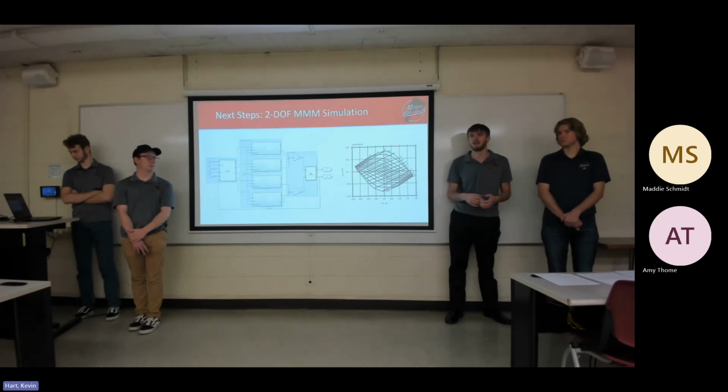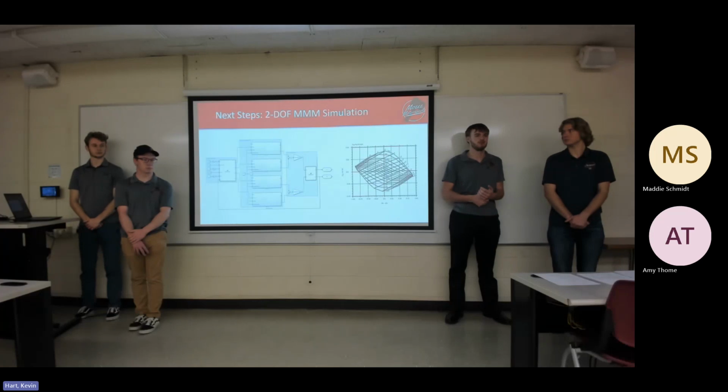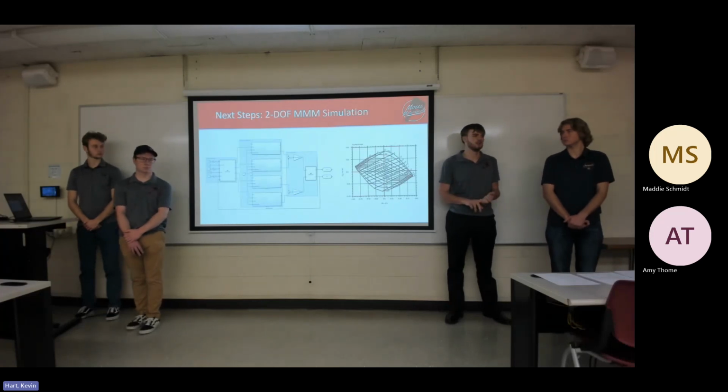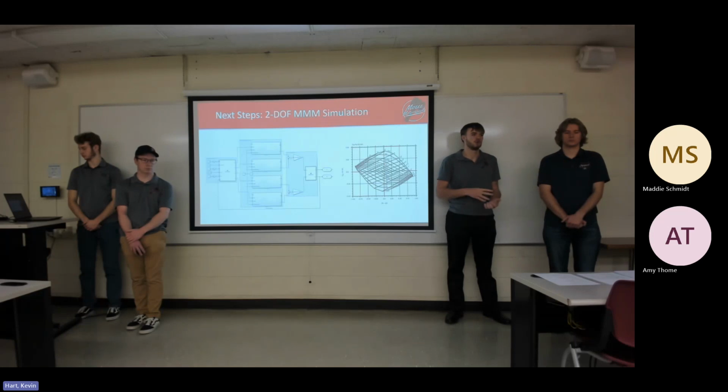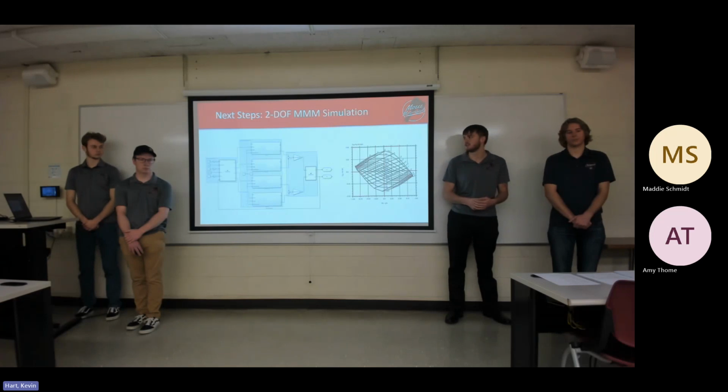where it will be best to create our slight amount of understeer by putting this point underneath this line, creating the maximum amount of lateral acceleration. Based off of that lateral load transfer, along with our target ride frequency and roll gradient, we are able to choose our spring rates and our anti-roll bar rates. Once we have these chosen, we can go into choosing our damping rates.